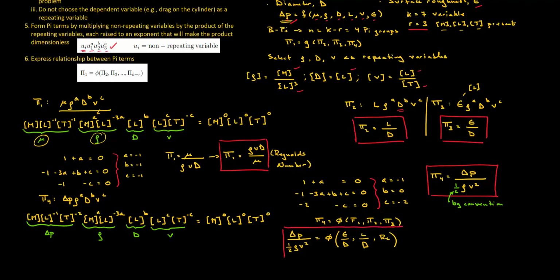So someone who is not running an experiment, but rather is just a practicing engineer, has a certain pipe, knows pipe flow, knows the Reynolds number, knows the surface roughness, knows the length between the 2 points, can evaluate the pressure drop by looking up results from a lab experiment and matching the Reynolds number, matching these non-dimensional lengths, and then solving for the dimensional pressure drop.